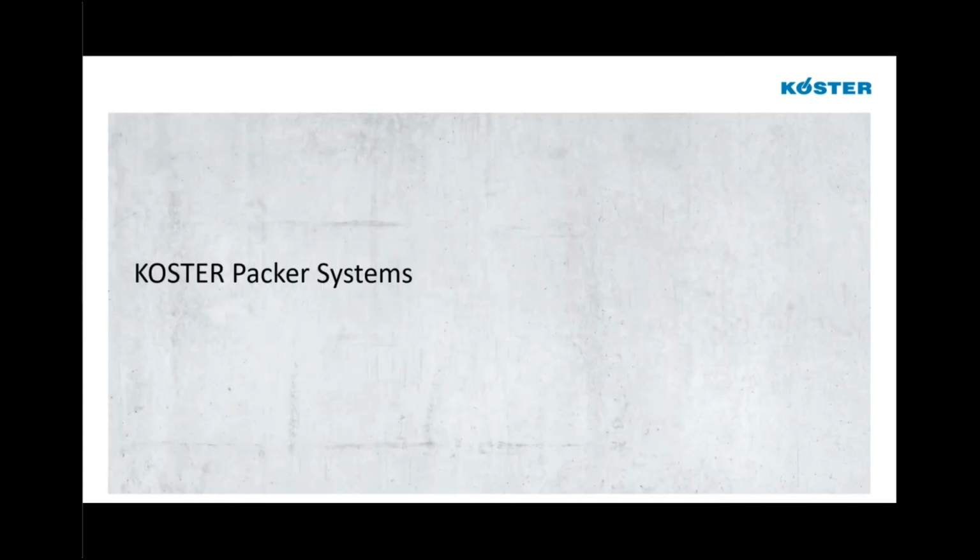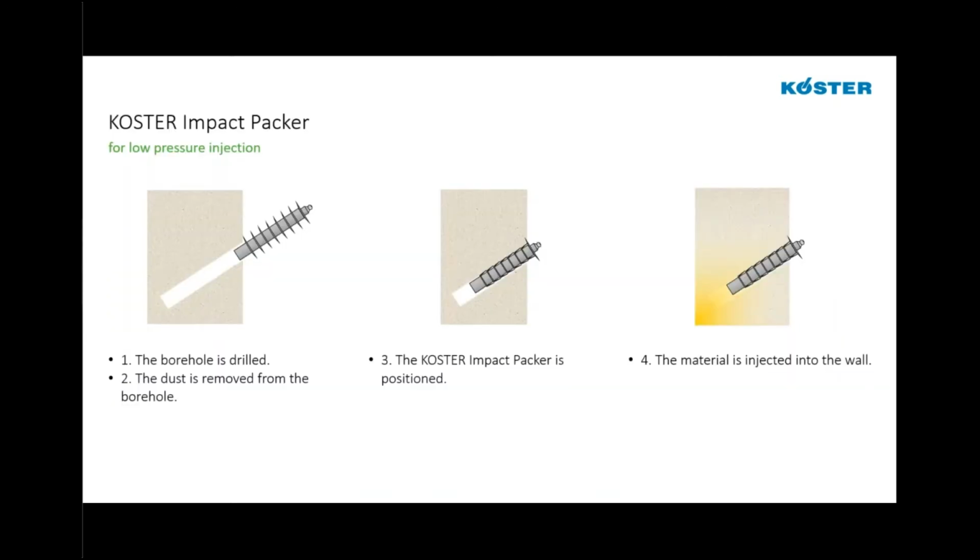The packer systems that we would normally use for crack injection. So we do have impact packers, bang-in packers, for very low pressure injections, where the borehole is drilled, that packer is banged in. These are sometimes called bang-in packers, and then the material is injected into the wall through that. More common than not, we're not dealing with very low pressure injections. So bang-ins are okay to use for low pressure injections, but commonly when we're dealing with injections, we want to